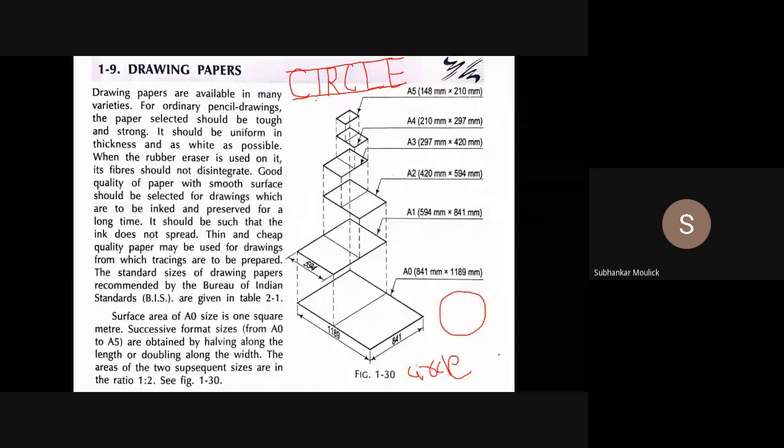Convert it into mm. Normally we talk everything in mm. So 0.5 centimeter will be how much mm? 0.5 centimeter is how much mm? Five. 5 units, mm. So keep one thing in mind. In between two letters, there should be a gap of 5 mm.